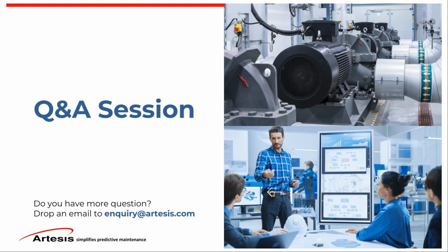How often does the spectrum update? That's a good question. The spectrum is actually updated every 1.5 minutes, and that's the default value. What the system does is capture a waveform every iteration. Each iteration is 90 seconds, and the waveform length is 6 seconds at 2.5 kilohertz. So that is constantly going on.